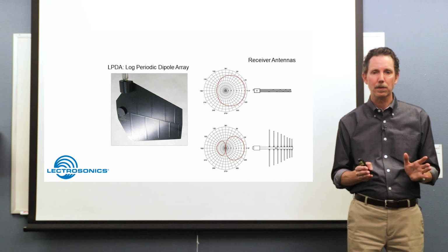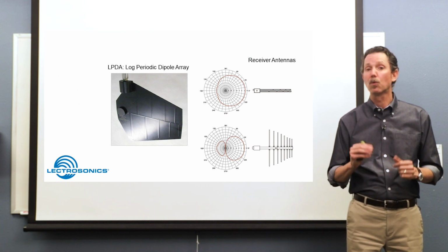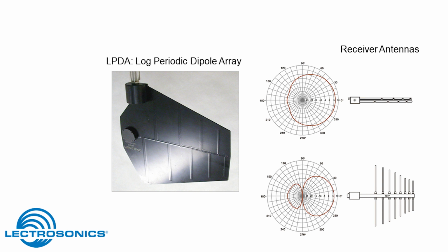Let's look at a different kind of antenna. These are the ones you see a lot in larger installations and tours. These are directional antennas, sort of like a directional microphone. They're going to reject signal from some directions and pick up stronger in the forward area. Now, these are not a laser beam. They have a directionality, but it is about 75 degrees from that center point in the lateral plane, sort of like a cardioid microphone. And from the vertical, they're more sharply defined, kind of like a hypercardioid microphone.